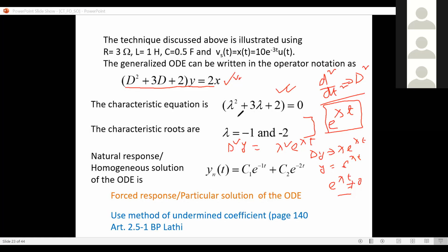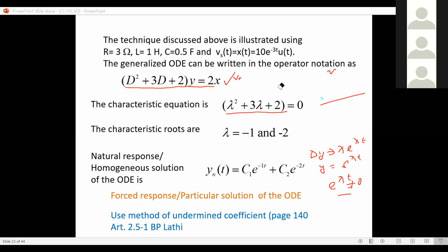Now the roots you have to find are those characteristic modes of your system. Those characteristic modes can be identified by solving for lambda. How many values of lambda will we have there? Two values. This is a quadratic equation of lambda, isn't it? Many possibilities could exist, but with the given values of circuit parameters, we obtain that lambda has two roots, and both roots are real and what? Imaginary? Are they imaginary? They are real, yes sir. Negative. Distinct.